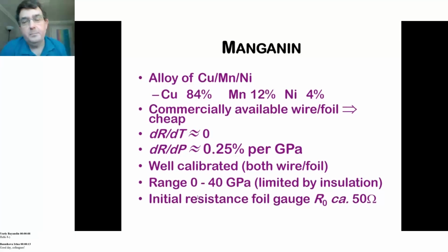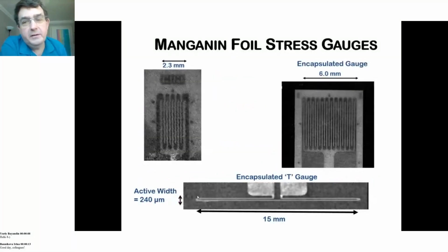Okay, these are just some pictures of what these gauges look like with some idea of the dimensions. They look like any other form of gauge, in the sense that there are some thick legs down which the power is delivered. There is a sensitive region consisting of thinner wires. So nothing particularly unusual there. At the bottom, we have an example of a lateral gauge. Now, please remember that with the two gauges at the top, the stress is going through the face of the screen that you're looking at. Therefore, it's compressing across the whole area of that gauge, more or less simultaneously.